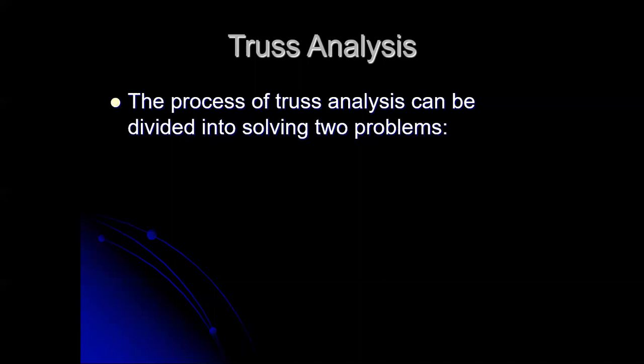So let's look at truss analysis. Last time I told you that truss analysis is a method of learning everything there is to know about a truss. We look at a truss as a structure that is intended to transfer external loads down to supports. And those loads transfer to the supports through the members that form that truss. The members carry a certain amount of load and they have a state to them. They are either in tension, being pulled apart, in compression, being squeezed together, or unloaded.